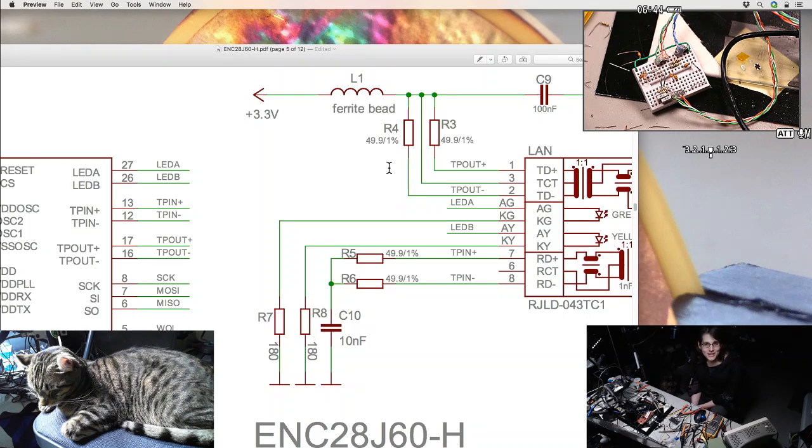It's like an open drain that leaks all the time, and so I tried replacing R3 and R4 with larger value resistors, and then I just ended up getting these very low voltages there. So it's like even when it's not transmitting, it's still sinking a decent amount of current. And there's probably a linearity reason to do that.